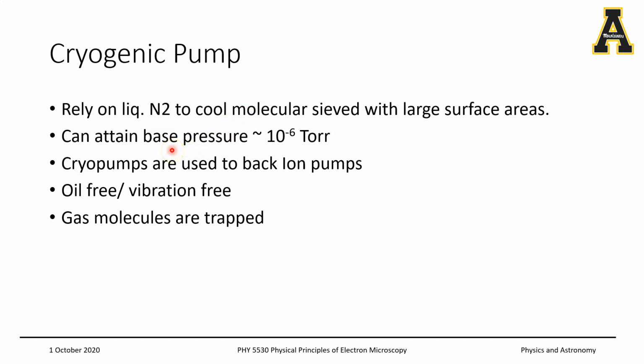And then using the cryo pump, you don't get extremely high vacuum. You will not be able to achieve the higher end of your ultra high vacuum conditions. But this is good for high vacuum to maybe the lower end of your ultra high vacuum condition, which is why cryo pumps are very popular as pre-vacuum pumps for your ion pump.